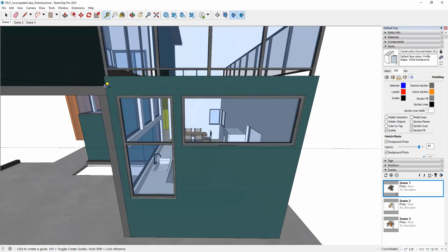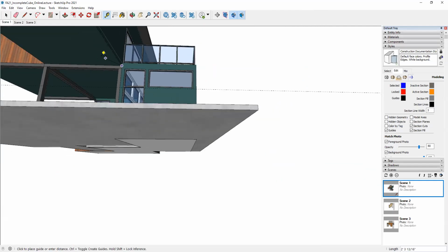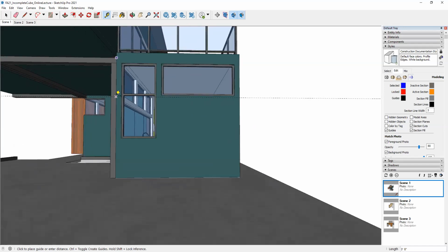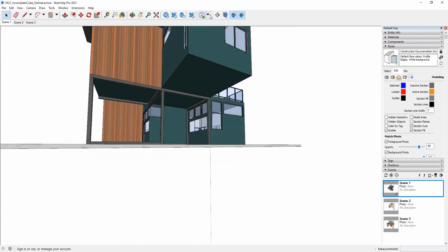And then say, okay, what's the height from this point? I'm selecting that point because that's aligned to the bottom of my surface, and bring this down. And my answer is 3 feet 8 inches. So when I create the section, I'm going to pull down 3 feet 8 inches. Go delete the guide. So we're going to hit the section marker, click right here.